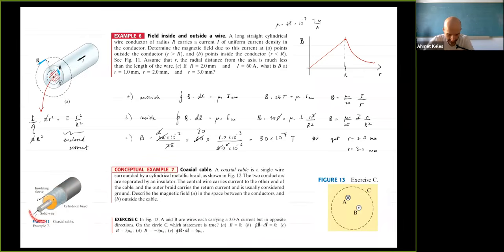And that's why, when you have sensitive signals to carry, like sound signals, if you are playing music and you want to use your amplifier, you generally use this kind of wire because you don't want noise from your speakers. This can shield outside noise pretty well. Or your TV cables, that's also a sensitive signal. You better have something that doesn't get affected by the outside noise.